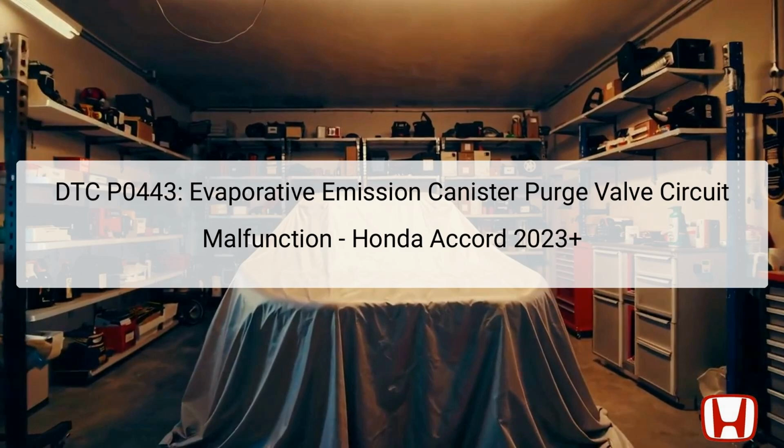The Evap system plays a crucial role in minimizing vehicle emissions by capturing vapor and preventing it from escaping into the atmosphere. The canister purge valve is responsible for allowing these captured vapors into the engine for combustion. Understanding these details helps in effectively troubleshooting the issue and ensuring proper remediation.